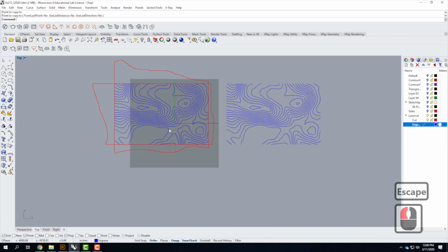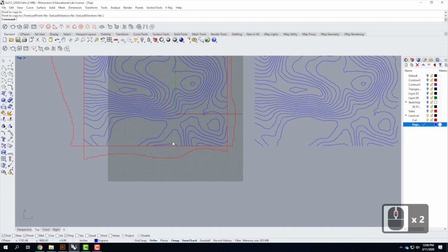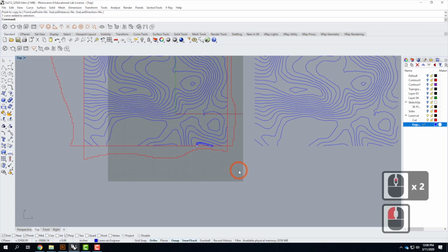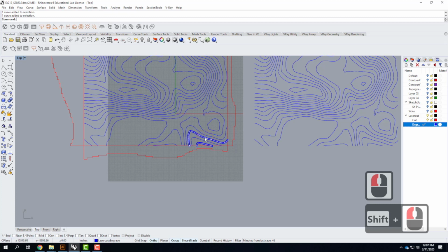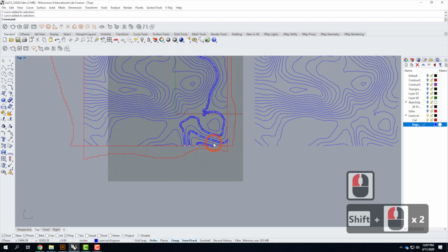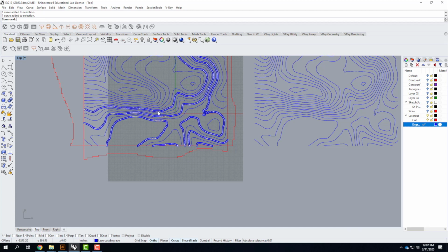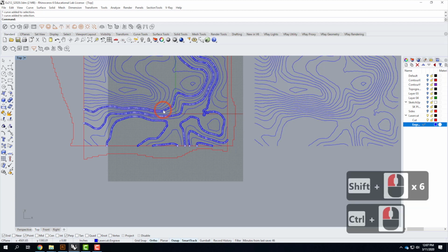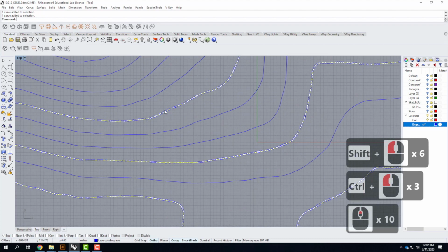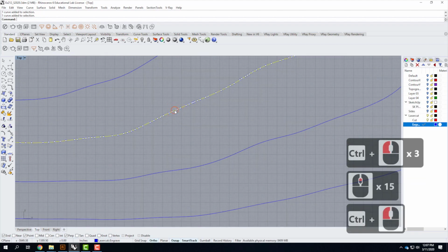On the first set, I'm going to start at a low point. So we'll pick, let's see, this is the low point. I can kind of see because of the side there. I'll select it, then I'll work my way up selecting every other contour. So I'll hold down Shift and I'll select this as my next contour. I'll select this as my next contour. That would be every other. That would be every other. This would be. That would not be. Let me zoom in here. Oh, come on. There we go.